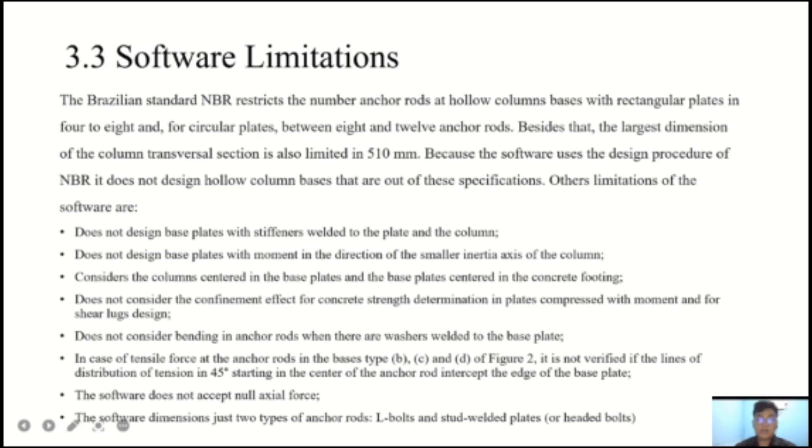In case of tensile force at the anchor rods, in the bases type B, C, and D of Figure 2, it is not verified if the lines of distribution of tensions in 45 degrees, starting in the center of the anchor rod, intercept the edge of the base plate. The software does not accept null axial force.